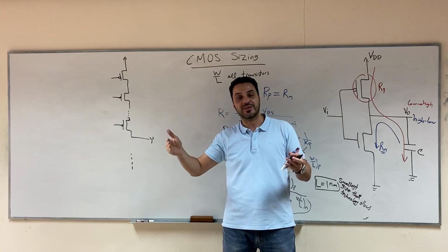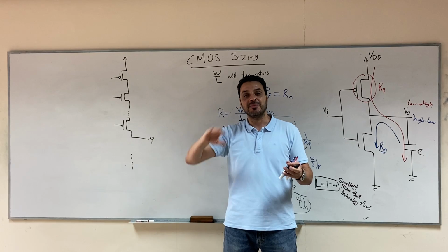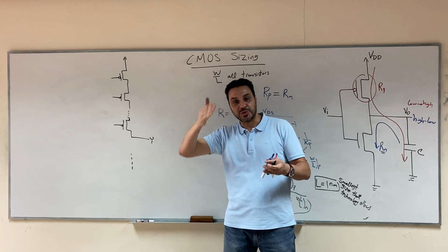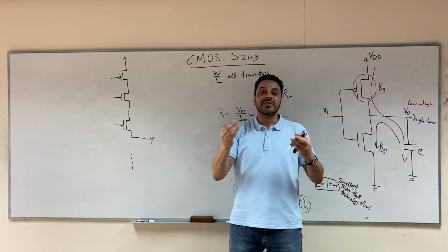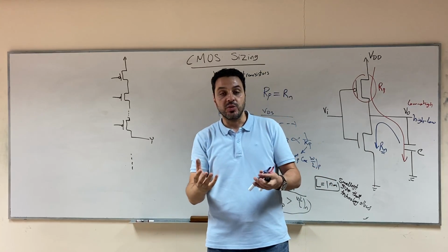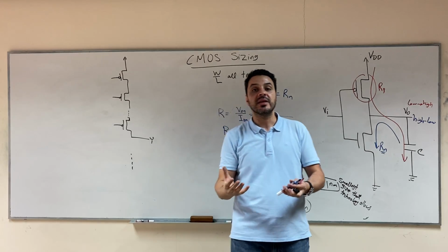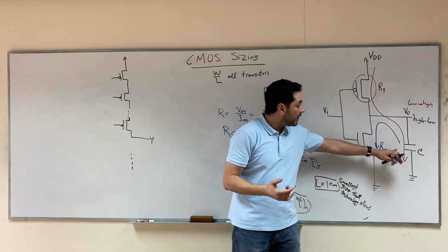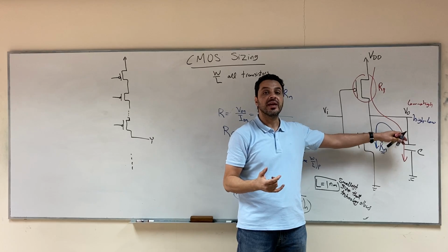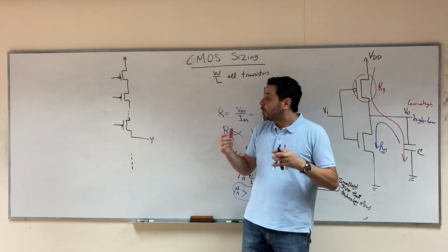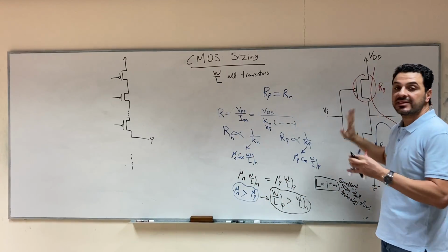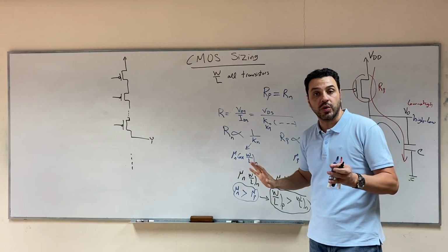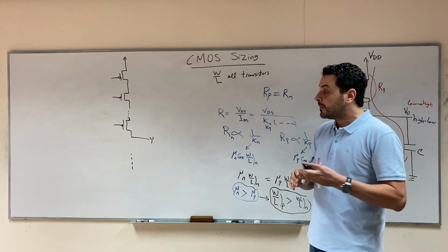If you use a higher frequency, the input voltage is going to change before the voltage of the capacitor goes down. So the maximum frequency that you can use depends on how fast this capacitor charges and discharges. So always when we design any logic gate, we are interested to have the same speed as the CMOS inverter, not slower. The same speed or more.